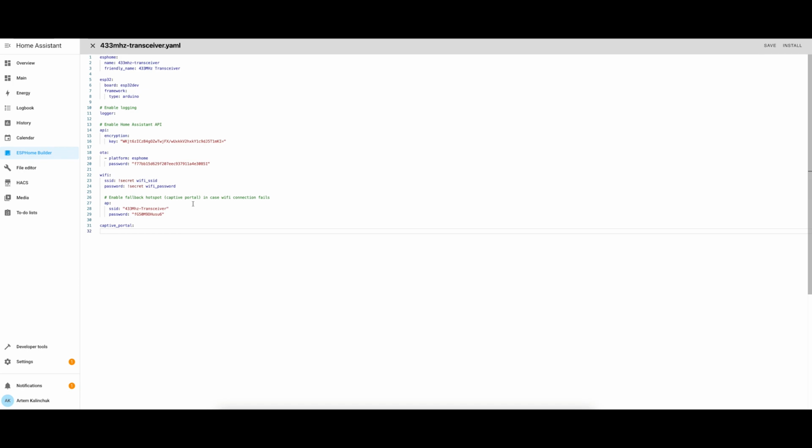So what we want to do now is actually add the 433 megahertz receiver module. The reason we only want the receiver for now is because we want to see what kind of codes are being sent by the remote. I just pasted here the remote receiver. The remote receiver component lets you receive and decode various common remote control signals such as infrared or 433 megahertz radio frequency signals. You can read more about it right here if you click on the link. It's on esphome.io.